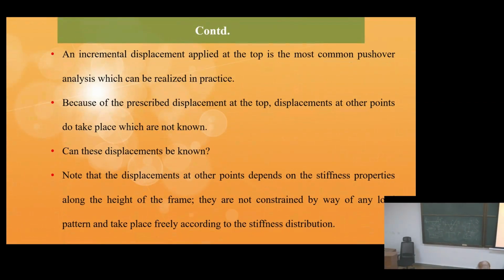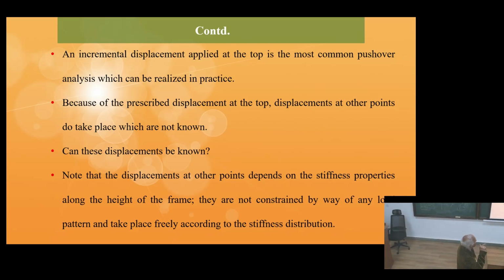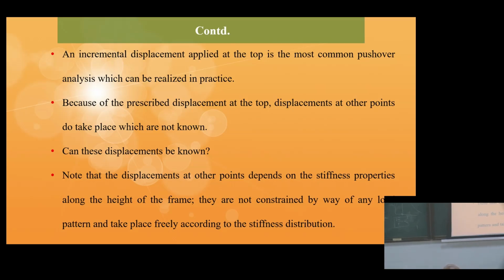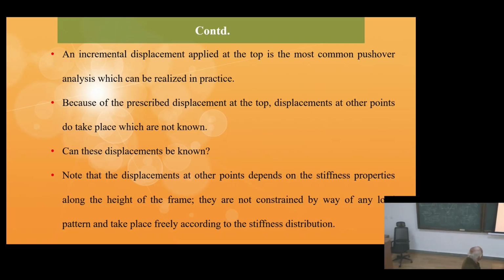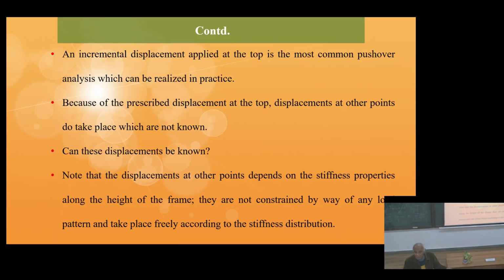An incremental displacement applied at the top is the most common pushover analysis which can be realized in practice. That means I am pushing the structure at the top only. That's the most common. Because of the prescribed displacement at the top, displacements at other points do take place which are not known. You do not know. I am pushing at the top. What will be the displacement at other levels? I do not know.